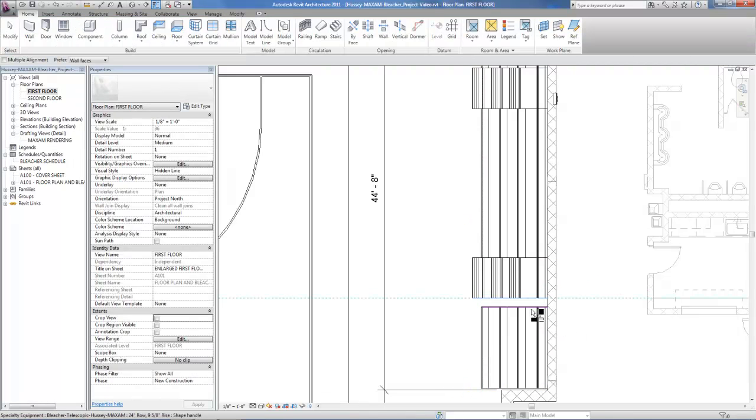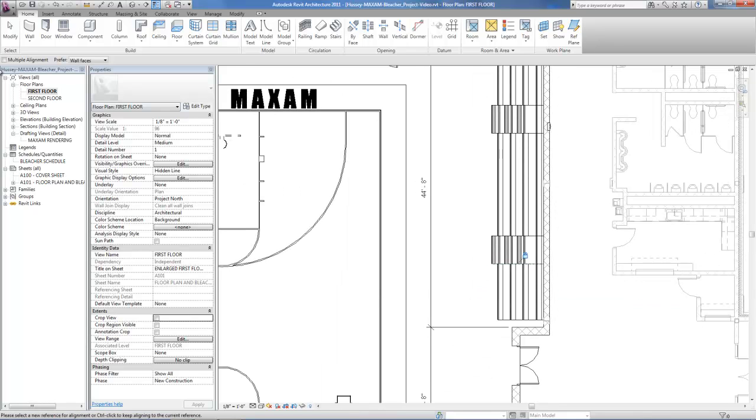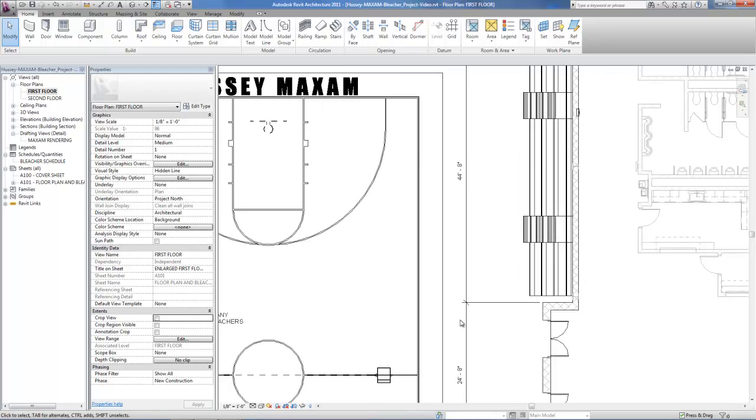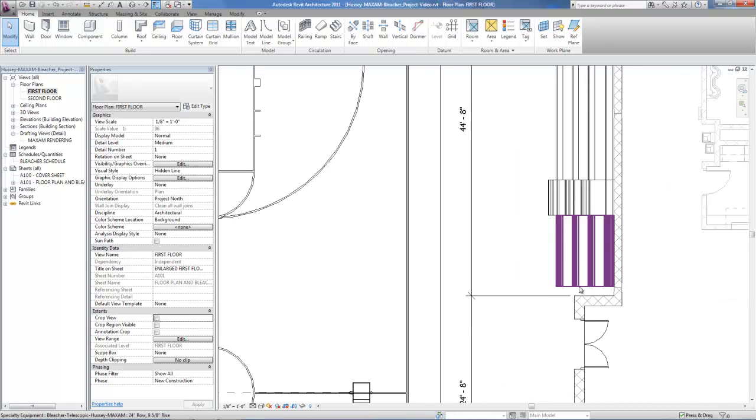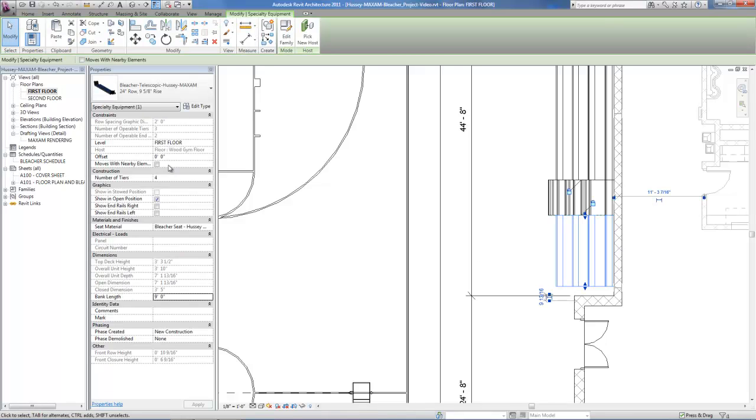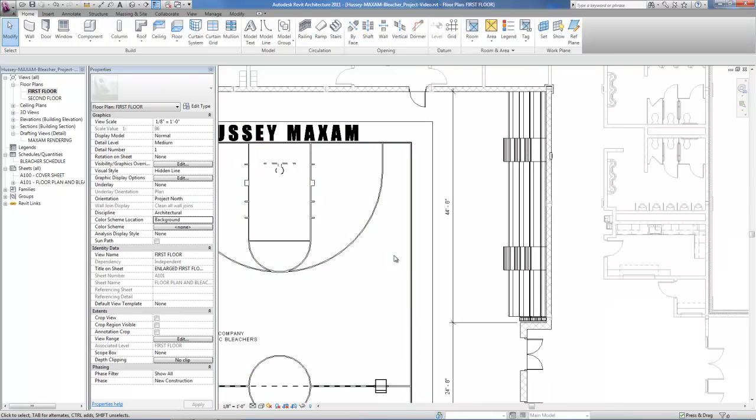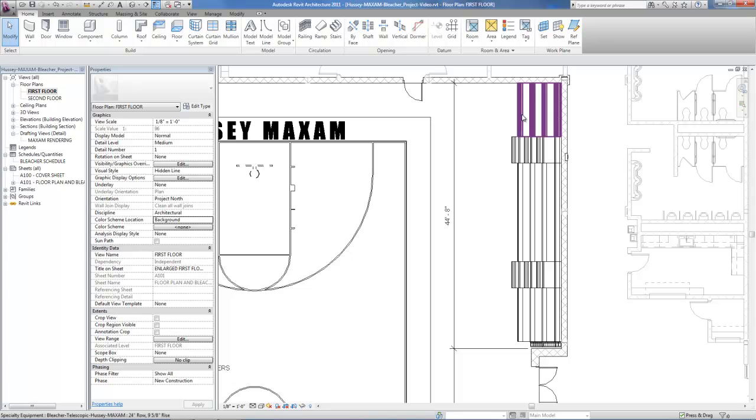We'll go ahead and align and lock it the same way as we've done the rest to complete our bleacher bank. Here, however, since we're not against a wall and we'll end up coming out further, we'll want rails. So we'll just go ahead and turn those on now. And there they are. Now the architect's ready to see how many rows of bleachers he can get in to really come out tight to the chord lines.